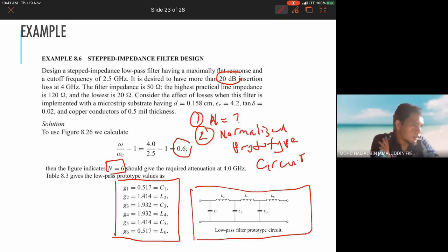Next step, you need to calculate the equivalent line or the electrical length, which is representing βL, either for the inductor or capacitor using the above formula. In order to do this, it's better for you to draw a table. So a table needs to be drawn.